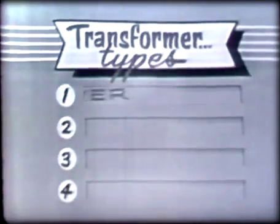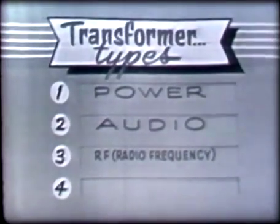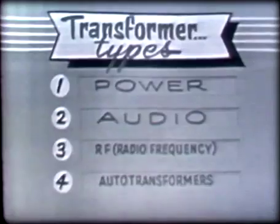Now, in general, there are 4 types of transformers. They include power transformers, audio transformers, RF, radio frequency transformers, and finally, auto transformers. Power transformers are used to step up or step down AC voltages occurring at the power frequency, which you'll recall include 50, 60, and 400 cycles per second. It should be pointed out, however, that a particular power transformer is designed to operate at only one of these frequencies. For example, a power transformer that's designed to operate at 60 cycles per second couldn't be operated at 50 and 400 cycles per second.